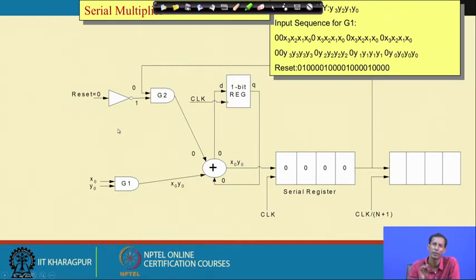This is the very basic multiplication. Because I am considering serial operation here, to generate the partial products, suppose 4 into 4, it needs 16 clock cycles. Then the addition operation again takes some time. So I have to wait if I consider more bits for multiplying.